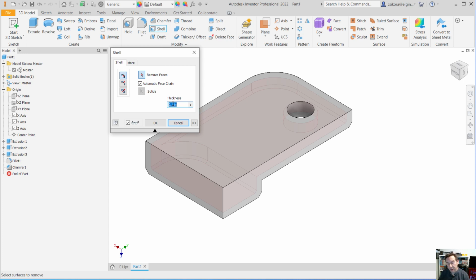Those of you who are going to be heading into manufacturing, some aspects of engineering, when you're making designs and someone says take off 60 thousandths, that means remove 60 thousandths of an inch if you're in the United States. And thousandths isn't the same as the mathematical thousandths that you learned in high school. This is different. It's like that 0.1 is 100 thousandths. 0.060 would be 60 thousandths.